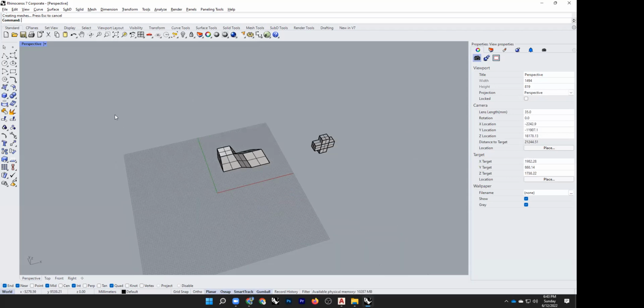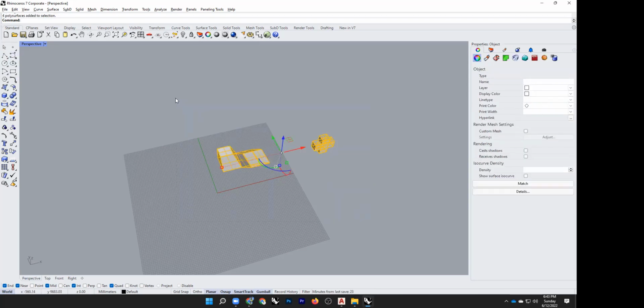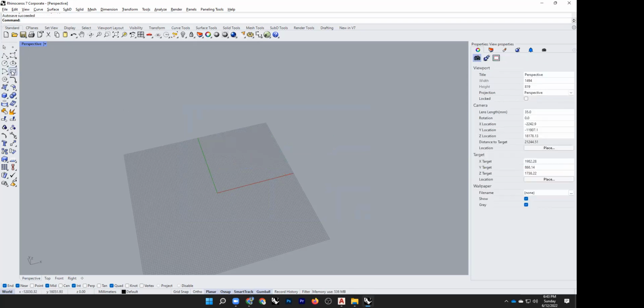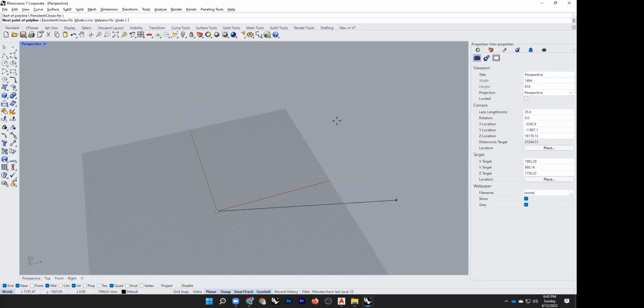And for you guys to start, I will show you just how to create lines, and from lines you can make models with whatever I already taught you. For example, you want to make a basic wall. What you can do, you can go to this polyline and you can make the dimension of the line. See, it's not 90-degree. For making it do everything in 90 degrees, you can press F8. So it will only move in 90-degree and along the axis.